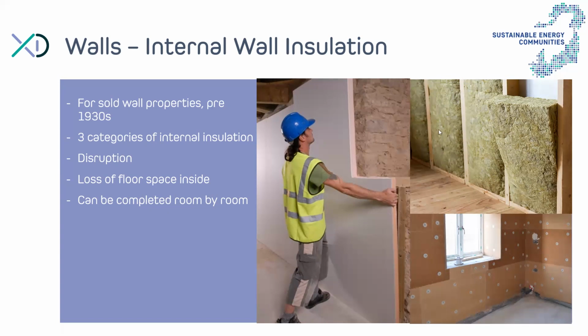You can also do it by placing timbers, vertical timbers, if I can call it that way, onto the wall, and then placing a mineral wool typically between those timbers, and then onto that you're fixing a plasterboard for your finish, right?